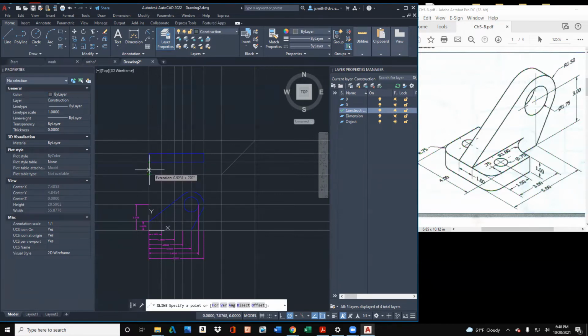So let's go ahead and come up here, 0.75 or 3/4 of an inch. Make sure it's 0. I'll do that again. Let's come from here because this is center. I'll type in 0.75. Enter. 0 degrees. That's good. So things that I can do now, believe it or not, is if I'm doing the construction lines, I can take these construction lines based on this and I can just snap it. And here are my construction lines because I'm going right off that 45-degree angle. All right, so I can go ahead and just build these.